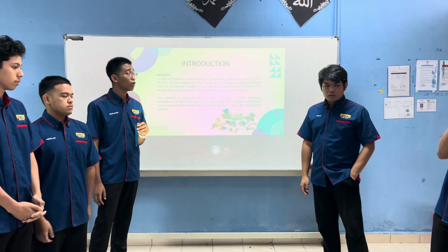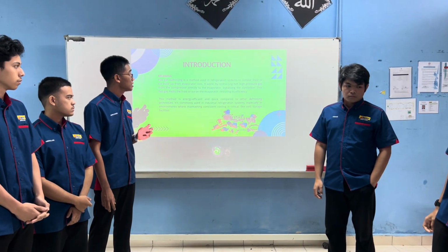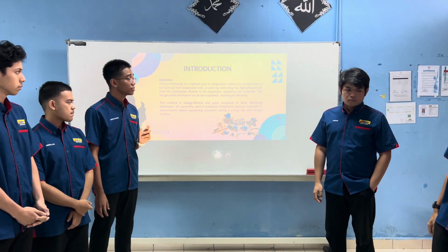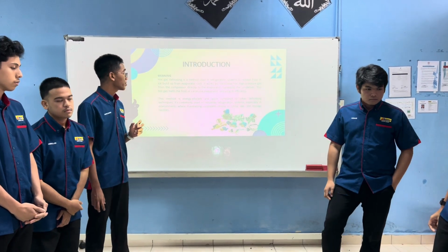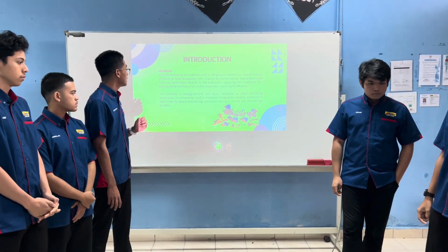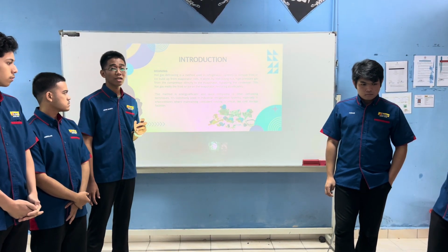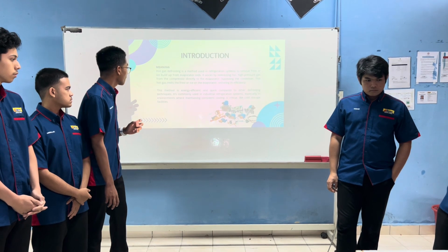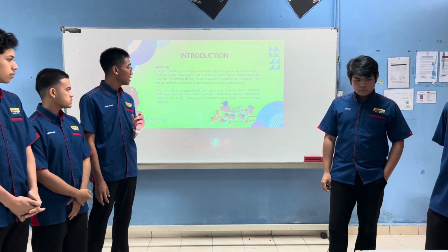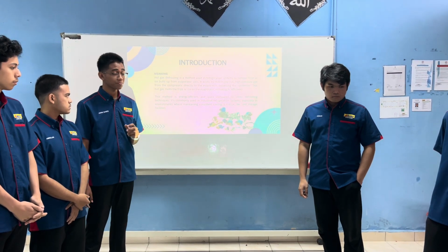System to remove frost or ice built up from the evaporator. It works by redirecting high pressure gas from the compressor directly to the evaporator, bypassing the condenser. This hot gas melts the frost or ice on the evaporator, restoring its efficiency. This method is energy efficient and quick compared to other defrosting techniques.